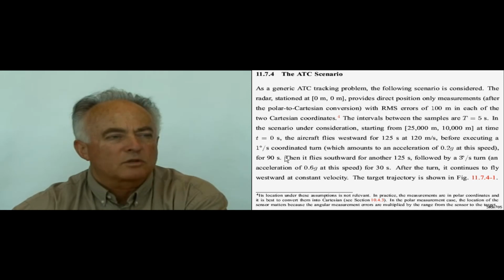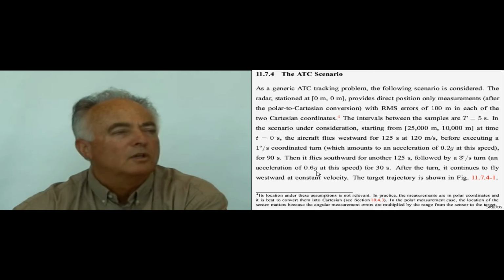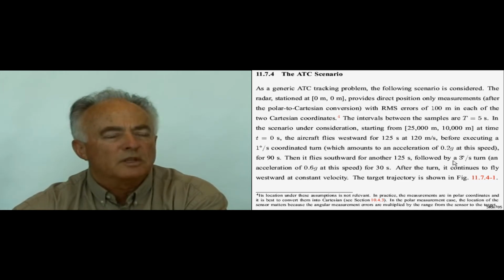Then it flies southward for another 135 seconds, followed by now a sharper 3-degree turn. This is 0.6 g. This is typically about the maximum that under normal conditions a civilian aircraft will undergo, for 30 seconds. So now it takes half a minute to make a 90-degree turn.